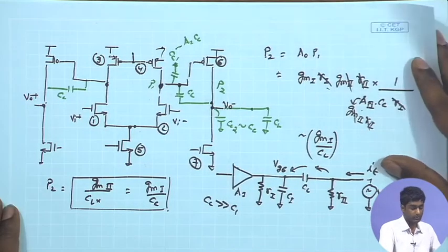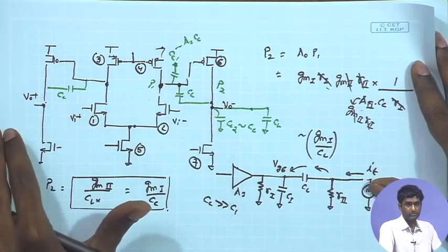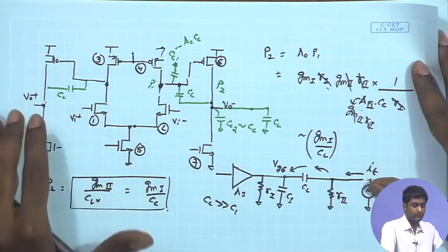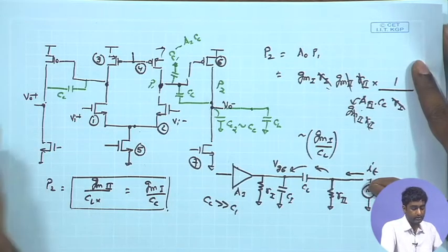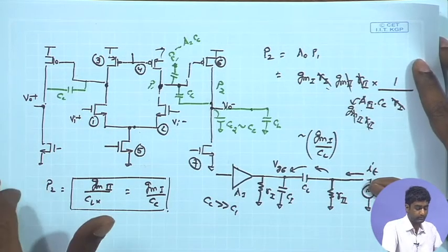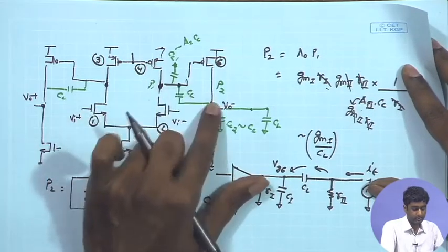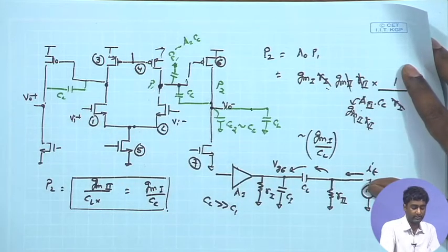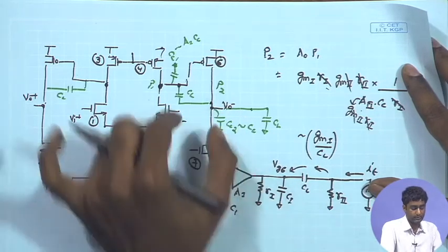Okay, so we can go towards the other issue which comes up with this CC, and that is the case of zeros. We have ignored throughout the zeros coming up in the differential amplifier or operational amplifier circuits, and they can also play a very crucial role in determining the overall stability. They can affect your stability in a negative manner. So, let us look at the concept of zero: how does it arise in this circuit, what is its effect on the overall phase response, and how to resolve that effect using some appropriate components added in the feedback loop.